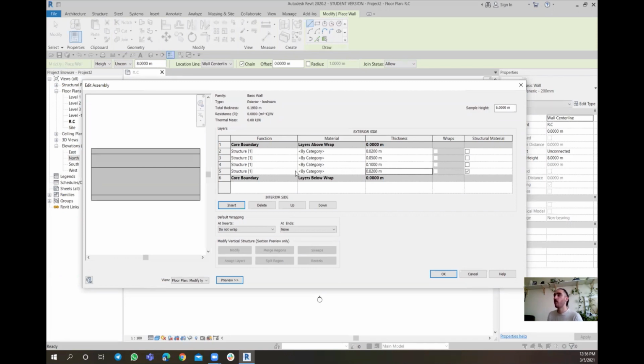So here, now I'm about to set up the function, meaning the wall composition function that happens to each of these layers. So I'm going to put this as finish 1, 4, or 2, 5. Doesn't matter which one you go with. The important fact is that you need to be clear in terms of which finish is getting assigned to which. That being said, I'm having, let's say, the interior finish under this, let's say finish 1, 4,